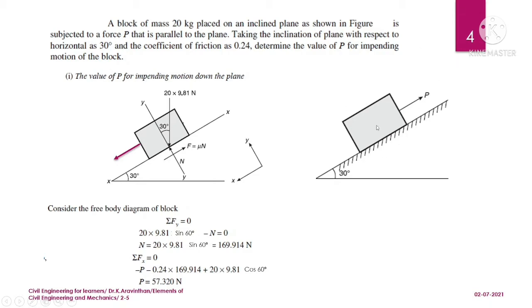Okay, let us draw the free body diagram using the given data. So you will have a self weight which will always act in a downward direction, which is purely 90 degree. You can see the self weight which is 20. It is given in terms of kg, so we will find it in terms of force. If you want to find it in terms of force, W into g. So W here is 20, and you have to multiply by 9.81. So you will get the self weight.